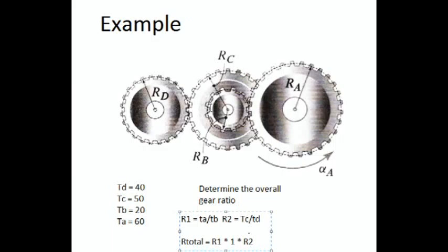The number of components in this equation should always equal 1 less than the number of gears in the gear train. And in this case, the 3 components shown for the 4 gears is correct. In putting our initial values into this equation, we obtain a ratio of 3.75.